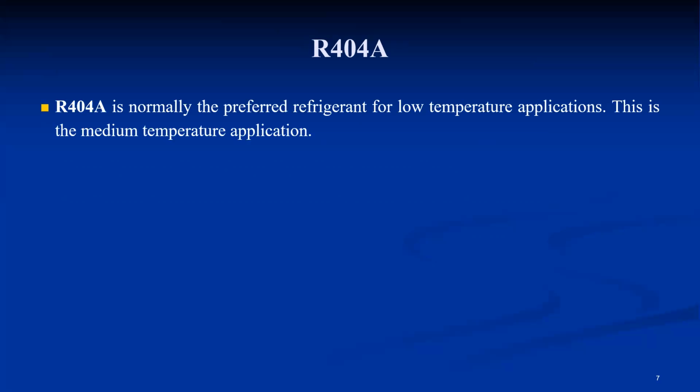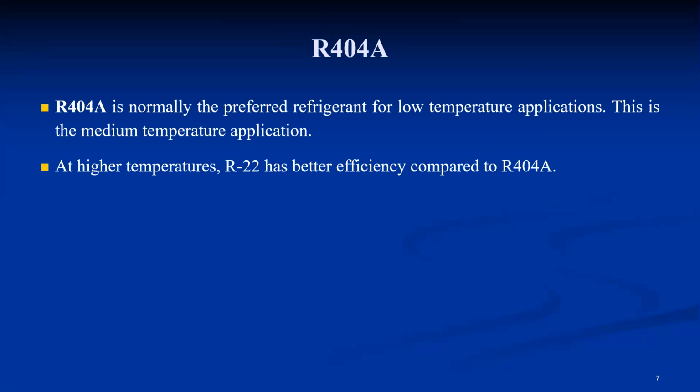R404A is normally the preferred refrigerant for low temperature applications. This is the medium temperature application. So 404A is especially suitable for very low temperatures, below minus 20 degrees Celsius, because of its lower boiling point. It's a blend of HFCs. At higher temperature, R22 has better efficiency compared to R404A.